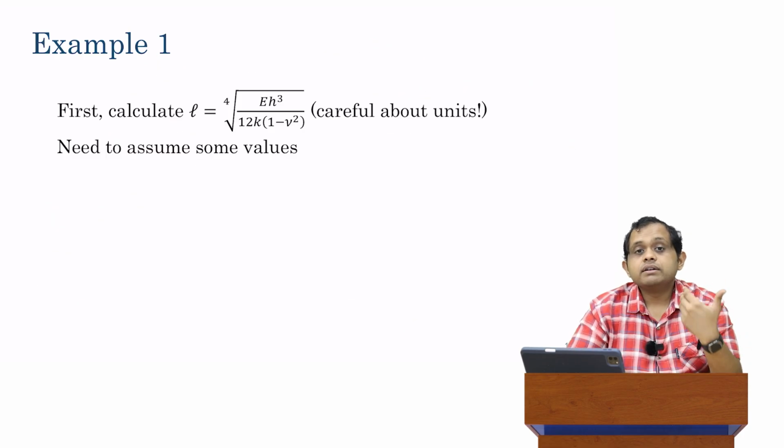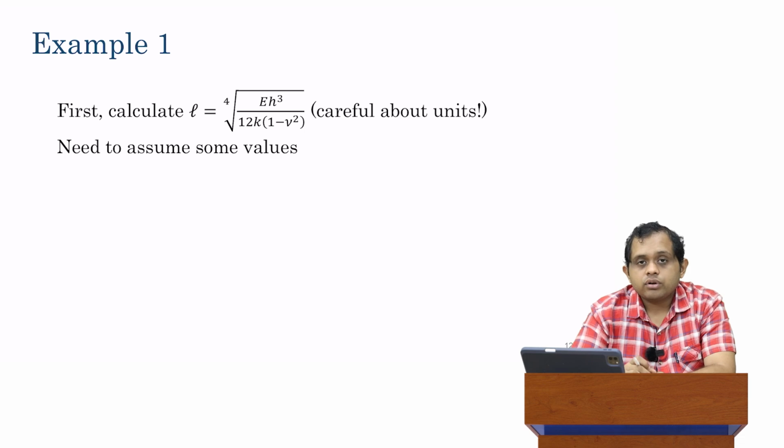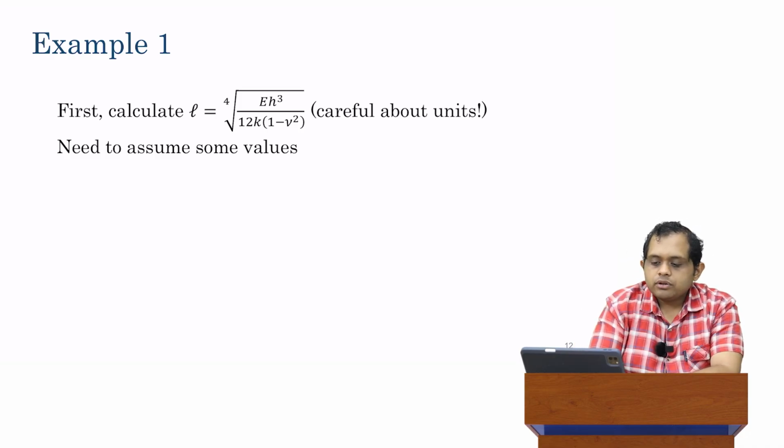That, by the way, is different from what we've been doing in the past. When we were looking at Westergaard theory, we used millimeters for the radius of relative stiffness. Now we are saying the answer must be in meters. If you use millimeters, your stress calculations using those regression equations will be wrong. So let's try to plug in a value. We are given L is the 4th root of. Now again, the answer has to be in meters, so we have to be very careful about units.